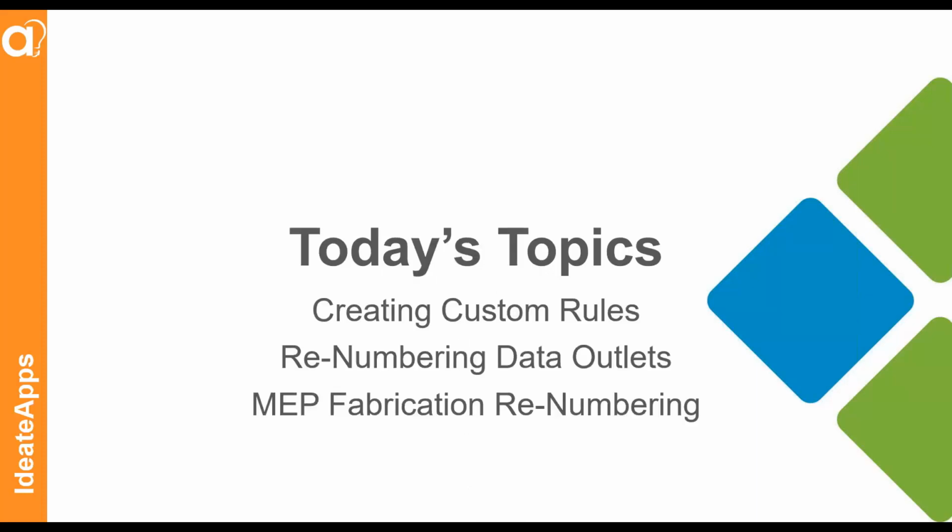So for today's topics, we're going to talk about creating custom rules. I'm going to focus on doing a little renumbering using some data outlets for today. Again, we can renumber many different items within Revit, but I'll focus on the data outlets. And also a little bit of MEP fabrication renumbering. These were some requests that came in from folks in the past, and so we started looking at how we can better assist with the fabrication renumbering process.